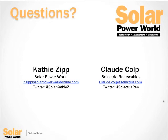For instance, if anybody happened to have looked at one of the last publications from a different solar trade magazine, they might have seen a residential system with a DC disconnect mounted on the gable end of a house up about 10 or 12 feet. And there were some comments revolving around that particular image saying, this is not what we intended, this is not what the code was talking about. No, you don't need a tool to turn this off, but this isn't exactly convenient.